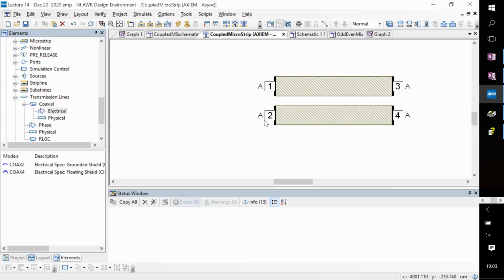Okay. The price you pay, of course, is that only 1% of the power you put in gets used up, but that's okay. Usually you don't care about that. And in fact, these kinds of directional couplers are central to measuring reflection coefficients in real instruments. That's actually how they separate out incoming and outgoing waves. It's a little bit more complicated than that. And I will discuss that towards the end, maybe in another 2 weeks or so, this whole network analysis measurement.